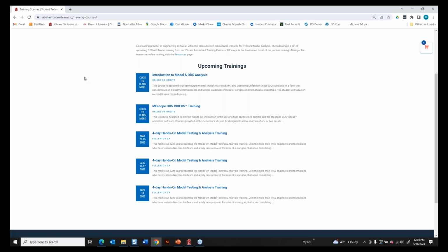is different than FEA. We take a set of mode shapes for a mechanical structure, and we model mass, stiffness, or damping changes to the structure. And SDM very quickly computes a new set of mode shapes for the structure, which reflect those physical changes, mass, stiffness, and damping. Well, with any mechanical system, what you'd like to know, and especially if it's machinery running in a plant or out in the real world, if the resonances change, can we correlate that with a physical change? Well, that's exactly what SDM does.